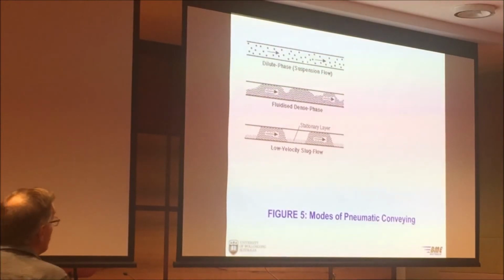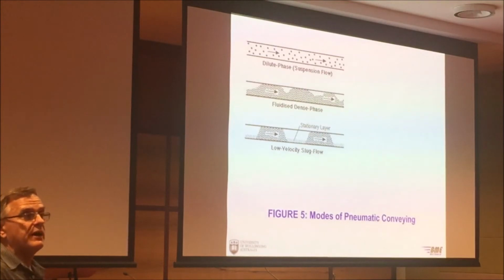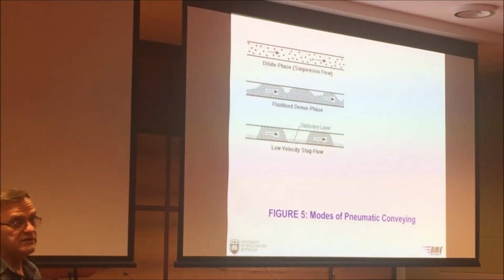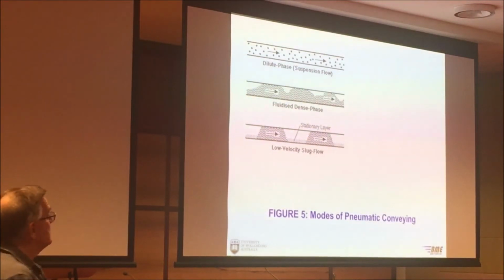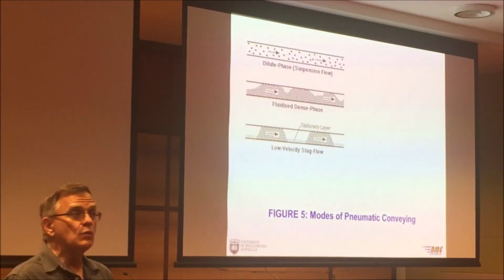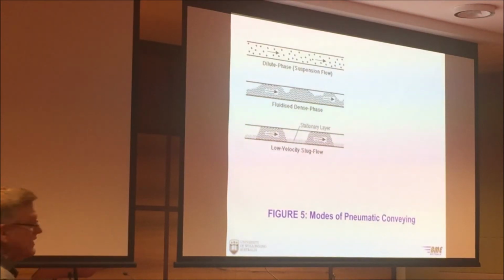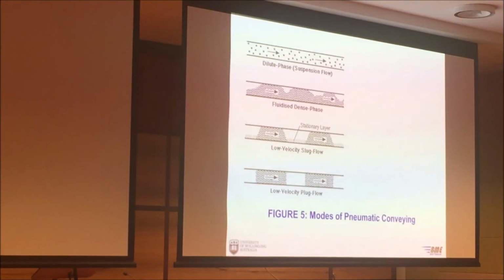Up here, if you've got an abrasive product, or wide size ranging material, you'll damage the particles quickly, and it also segregates during flow. Whereas this one is used for specific applications in the chemical and food industries generally. So for granular materials, we can do it in a slug flow. For cohesive powder, you need some device to break up the material, and you can create cohesive plugs. So we call this plug flow.